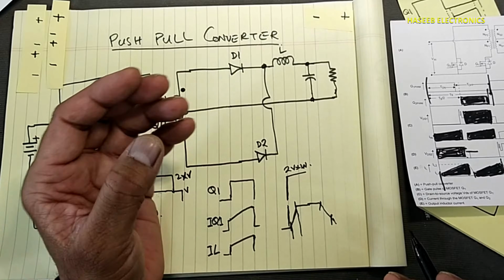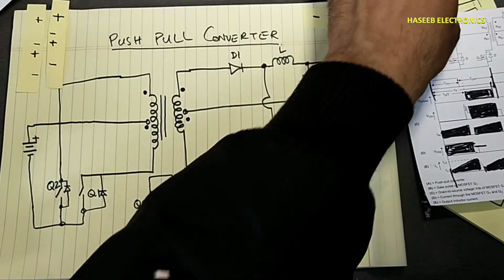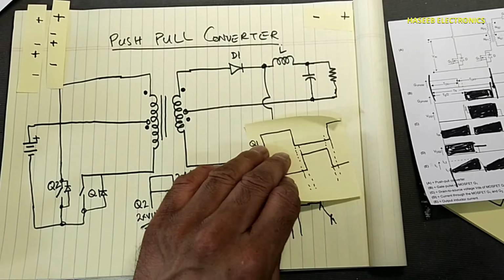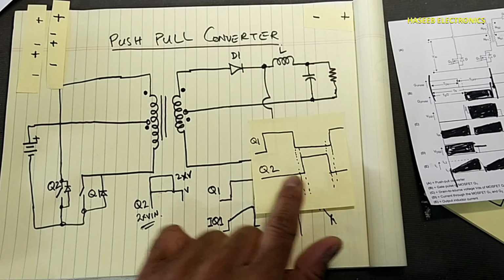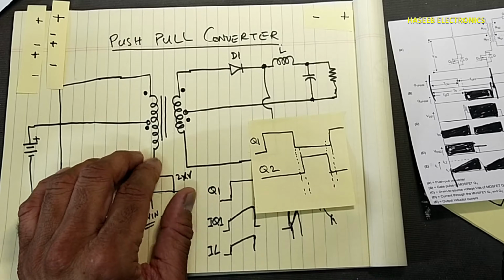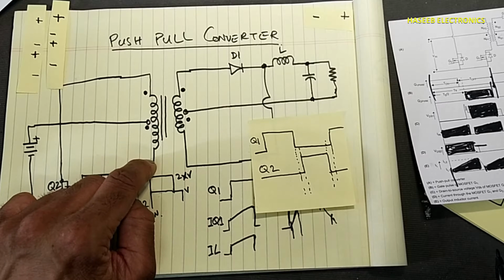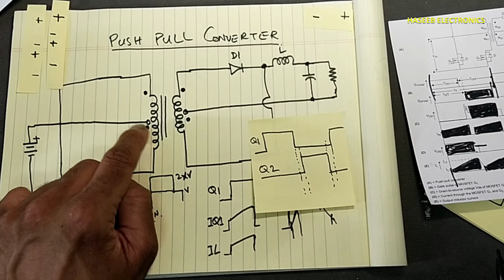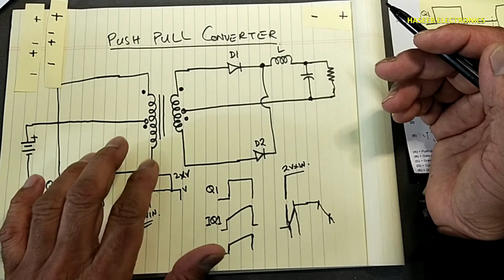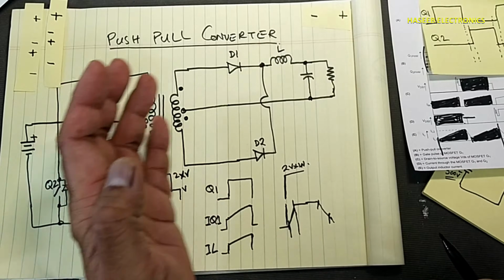If we compare with flyback, in the half portion we switch the transformer, and in the 50% duty cycle we demagnetize the core. But this topology allows a very small amount of time to demagnetize the core, and at the same time it will produce another switching cycle. So by means of bidirectional switching, we produce a bipolar magnetic field in the transformer, so it produces more power.